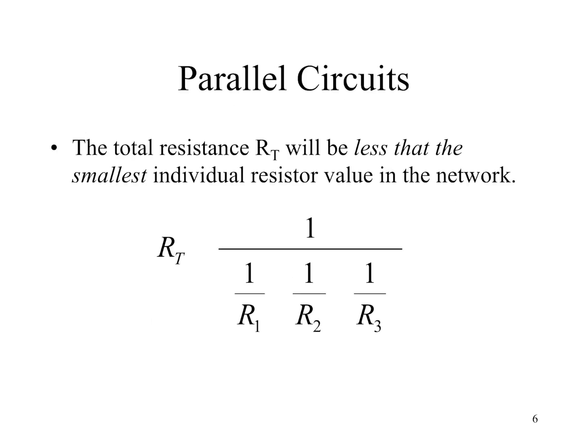When it comes to parallel resistance, we have an equation that looks like this: R total equals the sum of 1 over R1 plus 1 over R2 plus 1 over R3, and then you take the reciprocal of that sum. Once you've determined this sum, you take the reciprocal, or the inverse, of that sum. Now, what does that really come from?